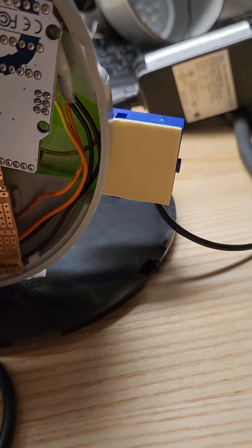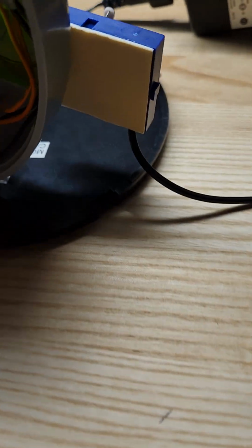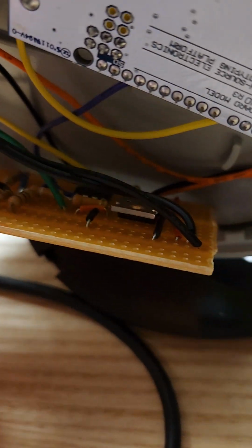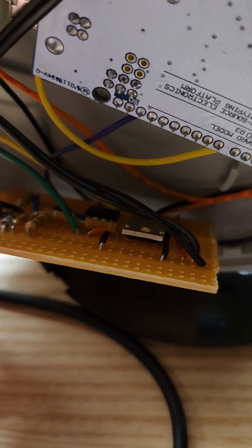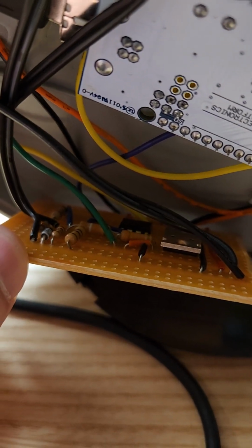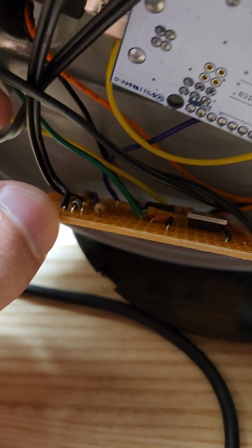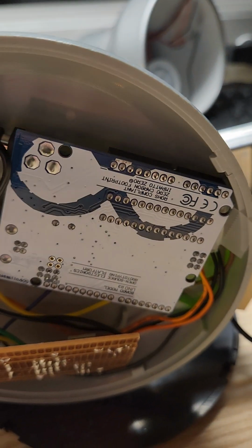This board here, if I can untangle it there, contains all the components for the circuit. I'm going to be careful here to not poke anything too hard. So this contains the op-amp previously discussed, the BJT that's used for the pulse width modulation, as well as a small Zener shunt circuit to regulate the voltage at 9 volts, which is the value used to power the Arduino. It's right in the middle of the operating range of 7 to 12 volts.